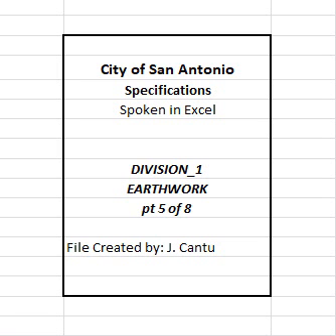Each layer is subject to testing by the engineer for density and moisture content. During compaction, the moisture content of the soil should not exceed the value shown on the moisture density curve, above optimum, required to achieve 98% dry density for soils with a PI greater than 15 but less than or equal to 35, or 95% dry density for soils with PI greater than 35, when required.